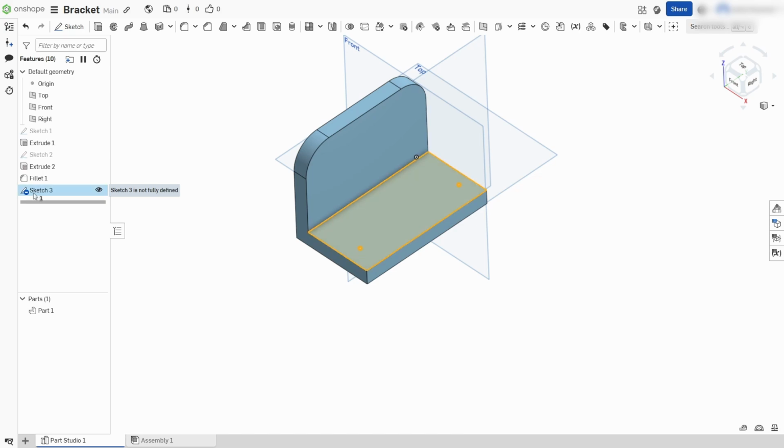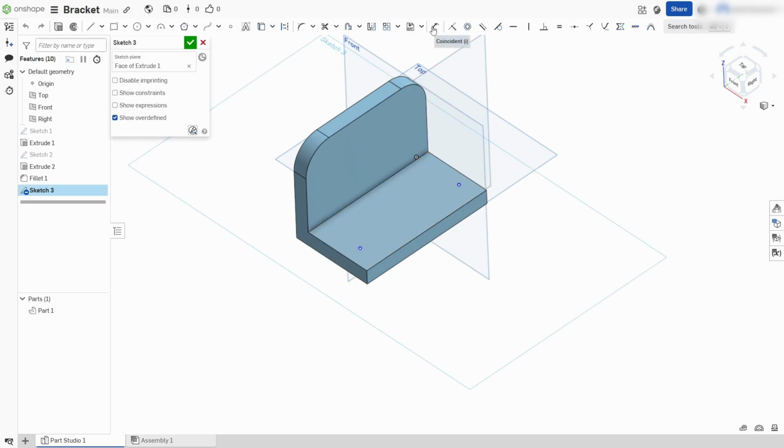So go back to sketch. We have to dimension this guy to here, and he is 25 millimeters. Same with this guy to here, 25. Okay, and then we want 19 millimeters from the edge. So here's this edge to here. We're going to choose 19. This edge to here, 19. Okay. So those are the points.